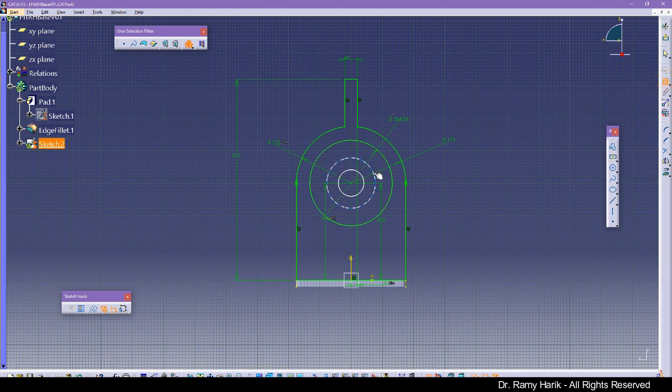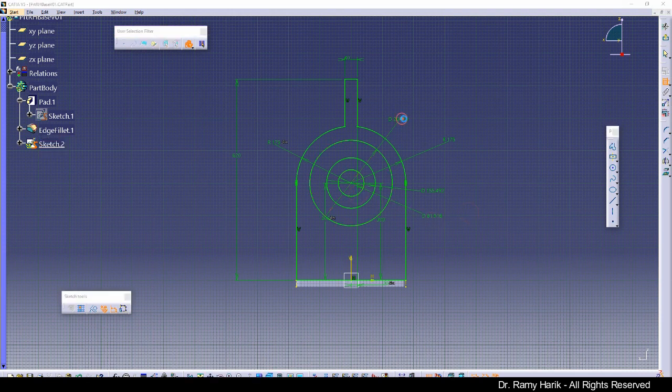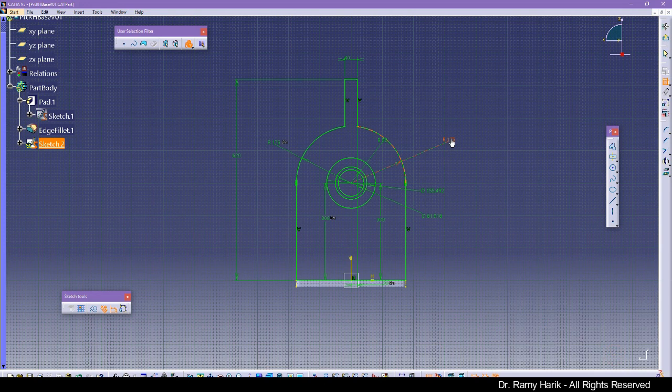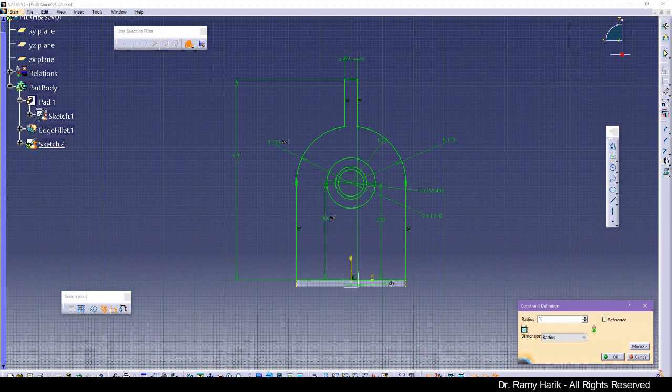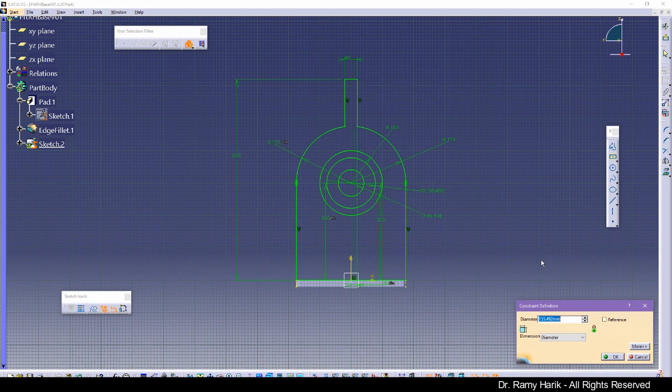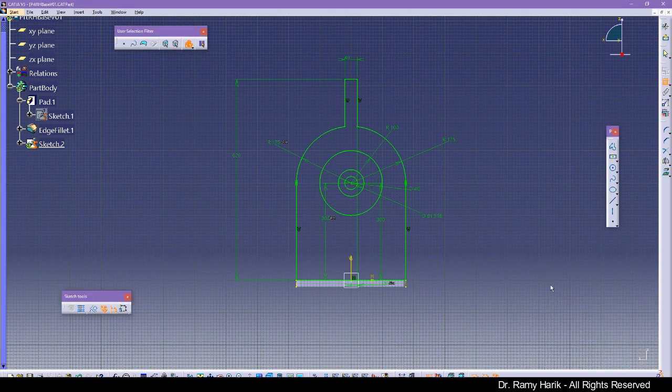And let's put the dimensions on them. Watch out, these are in diameter, so what's listed is radius. You can put 100, just make sure that you select radius here. So that's the 100 radius. What did I do? Oh, I changed it when I clicked radius. So 100 radius. This one we have a 20 radius or 40 diameter.